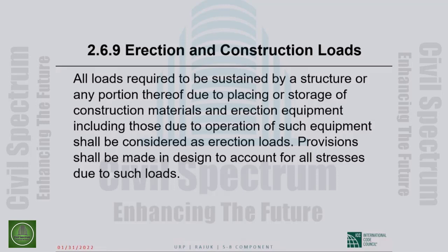So while the concrete is still green, I don't know, 4 or 5 days after construction, you will remove the shores, remove the formwork, but then we invariably reshore. We now install the shores directly supporting the concrete slab.